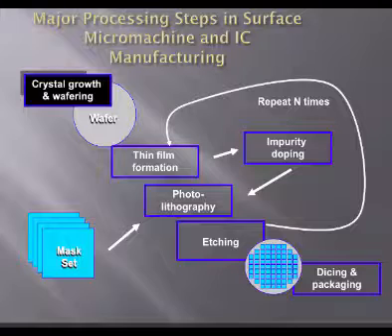We like to use surface micromachining because we use the same equipment as making computer chips. And MEMS can't be really, really small, can they? If you make them too small, they won't work. Right? You want to move stuff and you want to sense things, so you need a certain amount of area to do that. So you can make MEMS devices where the smallest part of it is 1 micron. The smallest space, the smallest spring width is a micron. Most of the time it's bigger than that.